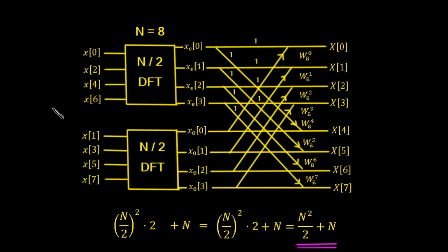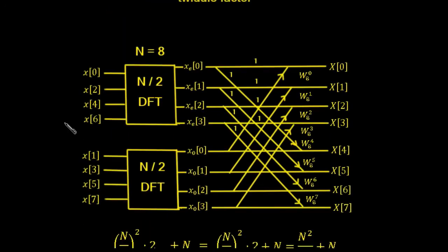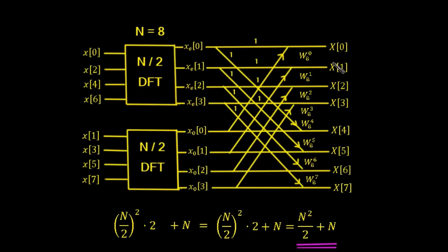So all we're going to do here is just follow this little algorithm here, and that's going to give us the final outputs here, which is our frequency domain on this side and our time domain on this side here. So from this we're able to look and see how this type of decimation by 2 is able to save us some multiplications.